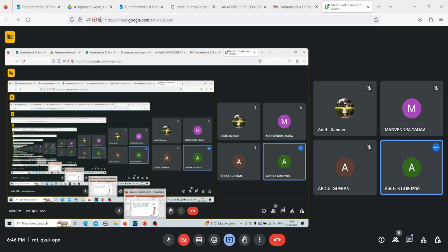We have all the parameters here. We do not know what is R square minus Ra square, but we know the mass of the water given. So the entire mass is in the annular region of this cylinder. So we calculate the volume of the cylinder, which is given as pi into R square minus Ra square into h. The volume can also be given as mass by density. You substitute the mass and density, and you can know the height of the tank, which is given in the question. From there you can find out R square minus Ra square, which is substituted back